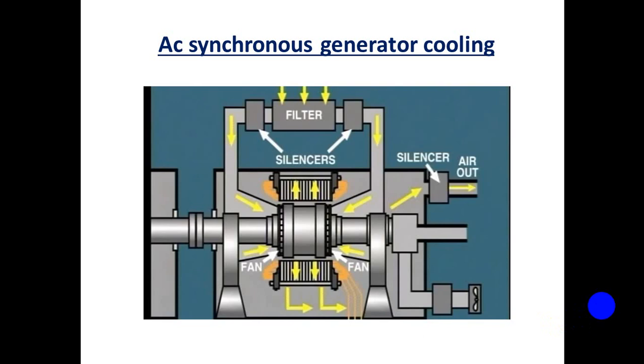Water is circulated by an AC motor-driven centrifugal pump. Cartridge filters are used to filter the water. These filters are designed to prevent metallic corrosive particles generated in the winding and piping from entering the winding hollow conductors.